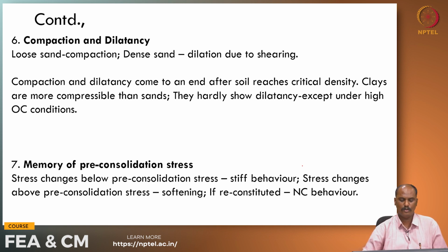The next factor is the memory of pre-consolidation stress. For stress changes below the pre-consolidation stress, the stress that the soil remembers, we have stiff behavior, and for stress changes above the pre-consolidation stress, we have softening behavior. We will see all these kinds of behavior in the subsequent slides.